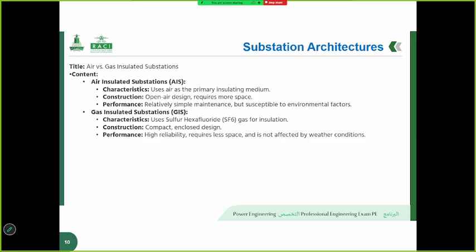The sealed nature of GIS makes it highly reliable and largely unaffected by external environmental factors like pollution, moisture, and extreme weather. This results in minimal maintenance and a longer operational lifespan. However, the initial cost is higher, and maintenance, when required, can be more complex due to the enclosed nature of the equipment.